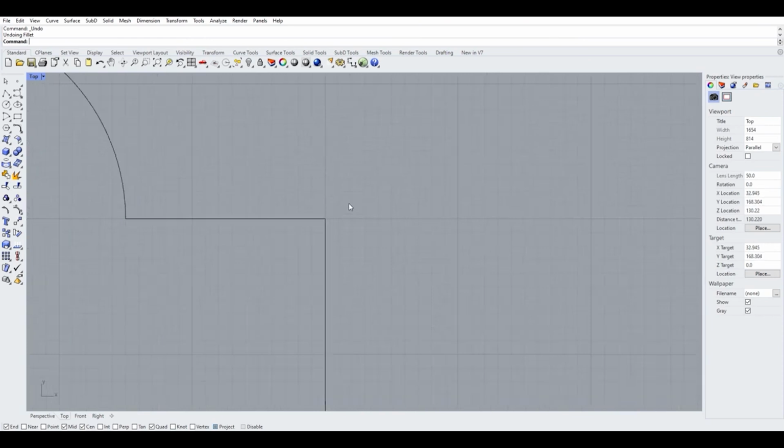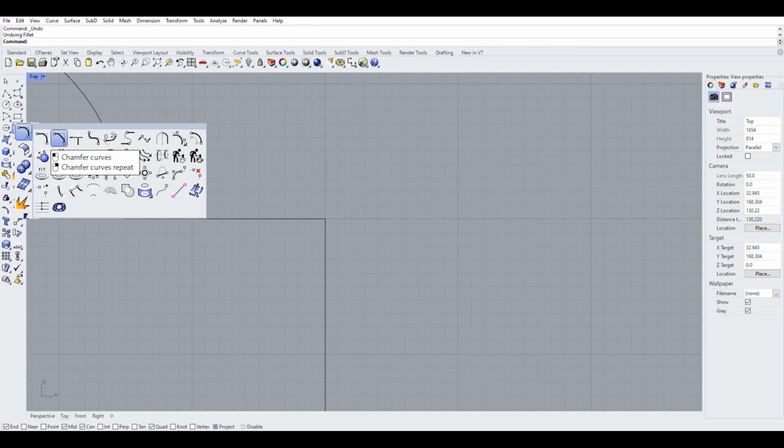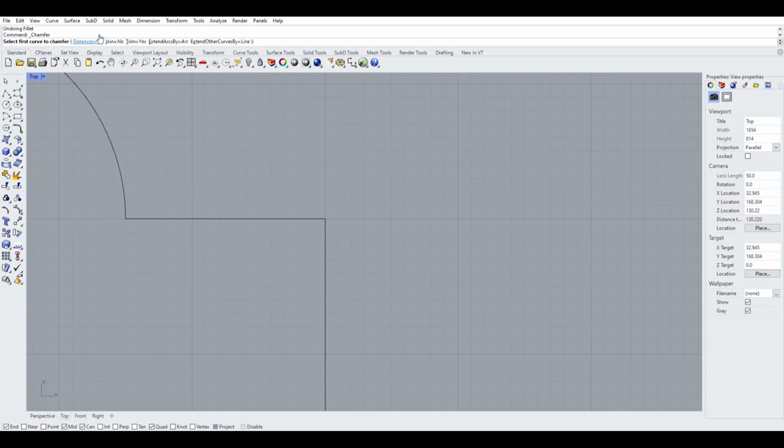Now, purely for interest's sake, you don't have to round out. You could use another action called chamfer. Chamfer cuts at an angle, but with a straight line. So under my tools, under the fillet tool, you'll find chamfer next to it. And again, we can define the chamfer distance before we start. So I'm going to click on distances. I'm going to type in 3, enter, and 3 for my second chamfer distance, because I'm cutting in on 2 different edges. And I click those two, and you'll see it cuts in 3 mil this way and 3 mil that way with a nice 90-degree angle.